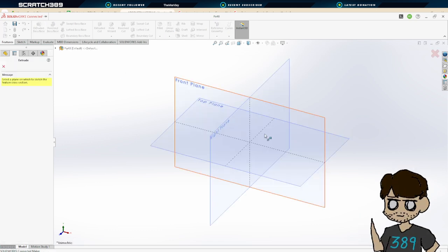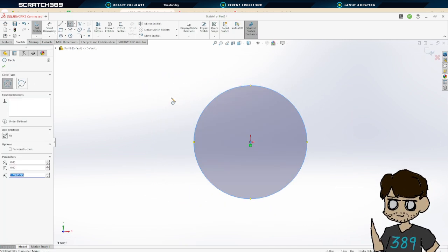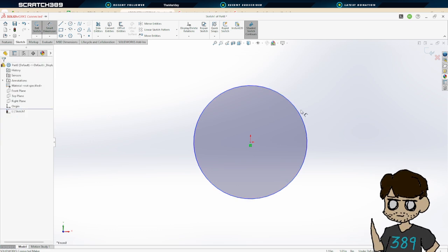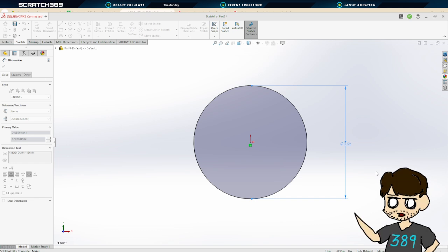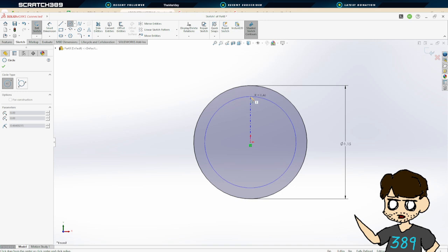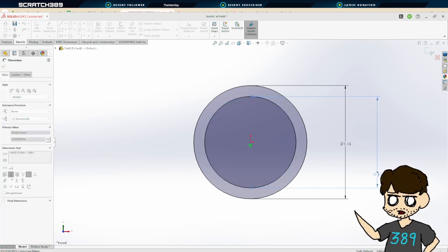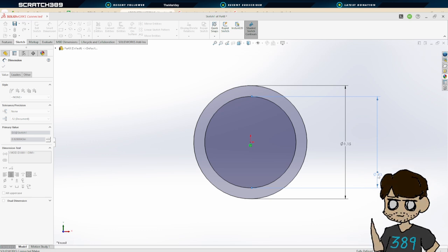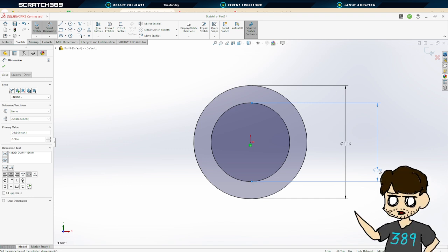So, let me make a general idea of what I was trying to say. So, we got, make this like 0.15 inches. Make the inner diameter a little loose, you know? I don't want it being exactly the same as the diameter of the pipe. So let's do like 0.85. Or maybe just 0.8. Good. I don't want it to be a super loose fit, you know?